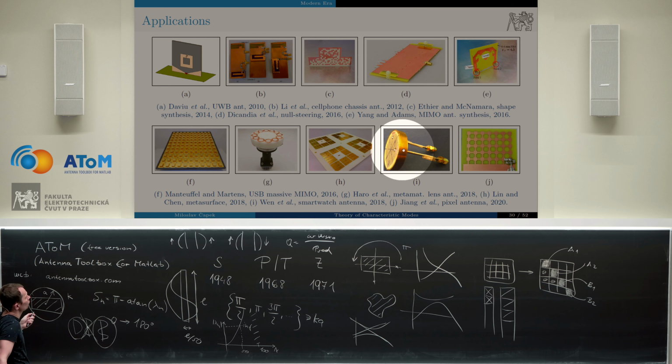My matrix is of size 730 times 730, which I have to decompose into characteristic modes. Or, on the contrary, I live with the fact from the beginning that the feeders are placed like this, which is very meaningful for a pixel antenna. In that case, I have only 31 degrees of freedom, and all the matrices can be compressed to that size.